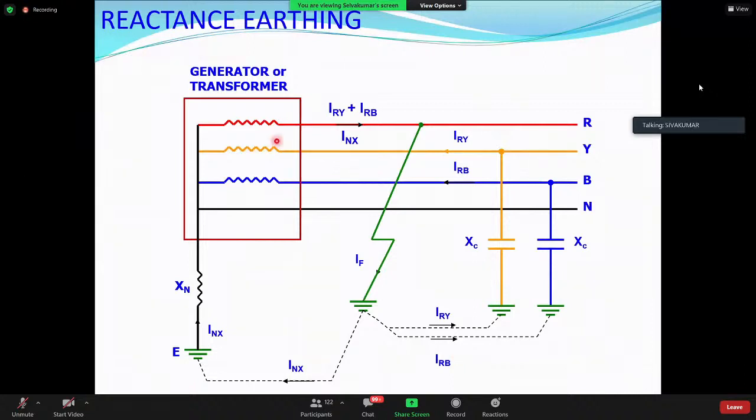Then here also there are two types: low reactance grounding. Low reactance grounding, typically the current is limited between 300 to 1000 ampere, where detection is easy. 300 ampere to 1000 ampere, you put the appropriate CT and detect it. Again, various choices are given. Customer can do his own system, case to case basis. You can do his cost benefit analysis for going for each and every system.